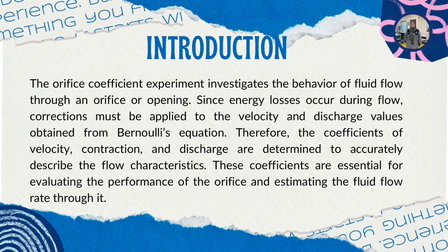Introduction of orifice coefficient. The orifice coefficient experiment investigates the behavior of fluid flow through an orifice or opening. Since energy losses occur during flow, correction must be applied to the velocity and discharge values obtained from the Bernoulli equation. Therefore, the coefficients of velocity, contraction, and discharge are determined to accurately describe the flow characteristics. These coefficients are essential for evaluating the performance of the orifice and estimating the fluid flow rate through it.